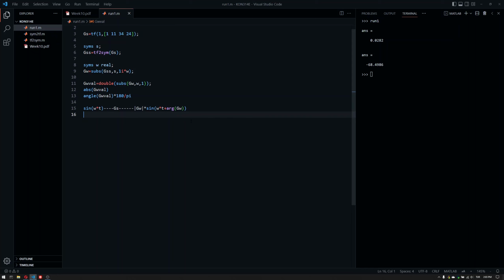So therefore, we have this Bode plot, which gives us the absolute value and the phase, so the gain and phase. So I can, for example, conclude that if I have sine t, it will be rejected or attenuated to a higher degree, because we see that the corresponding gain is quite low. And then if we go on with that, we will see what happens at each frequency.